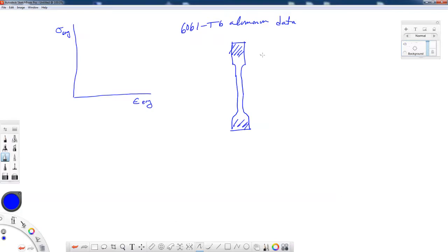And when you use what are called electromechanical testing machines with mechanical wedge grips, the grips are in here. These are the jaws, and they have an angle to them, and they sit inside a grip housing that has a matching angle.